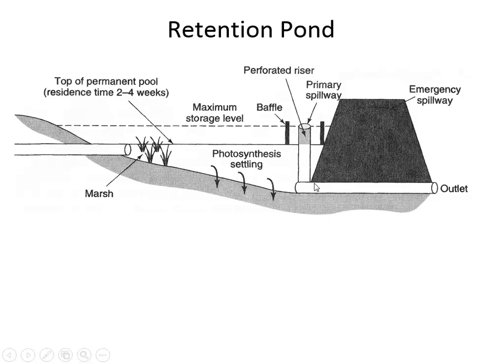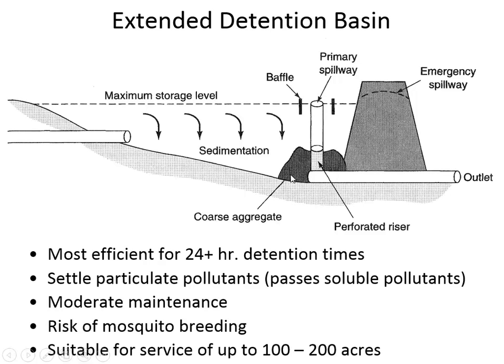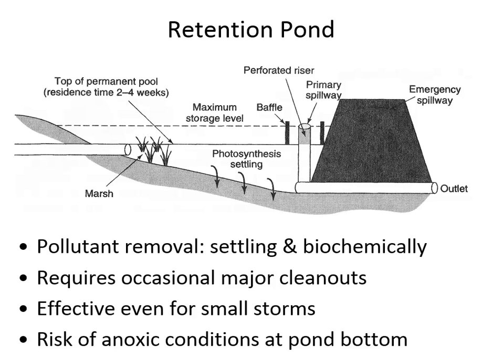And this pipe right here isn't open to the pond. In the previous case, you could have the outlet open to the pond at the bottom of the pond. But in the case of the retention pond, it's not. And you'll usually have a longer detention time, in this case, retention time. You'll see the retention time is 2 to 4 weeks rather than 24 hours in the detention pond.